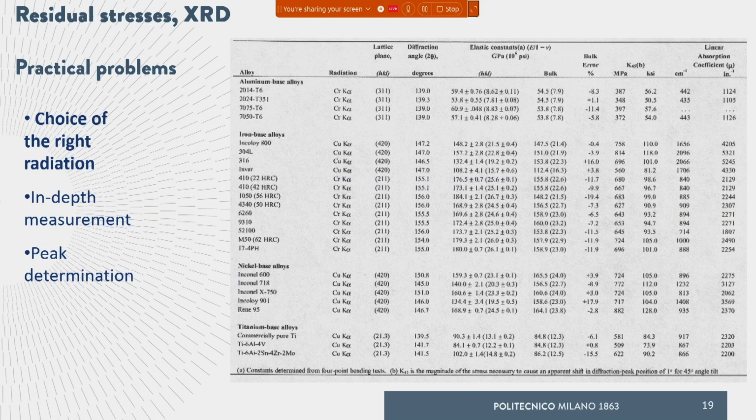Yes. Okay. Sir, in this, as we can see, the 2 theta angle, we have gone up to 140, 150. The diffraction angle, we have gone up to values of 140, 120, 130. But in general, mostly when we do experimental studies for obtaining XRD peaks, we limit our study from 10 degrees to maximum like 80 or 90 degrees. So for the residual stress measurement, is it the reason why we are going for diffraction angles till 140 or 180?